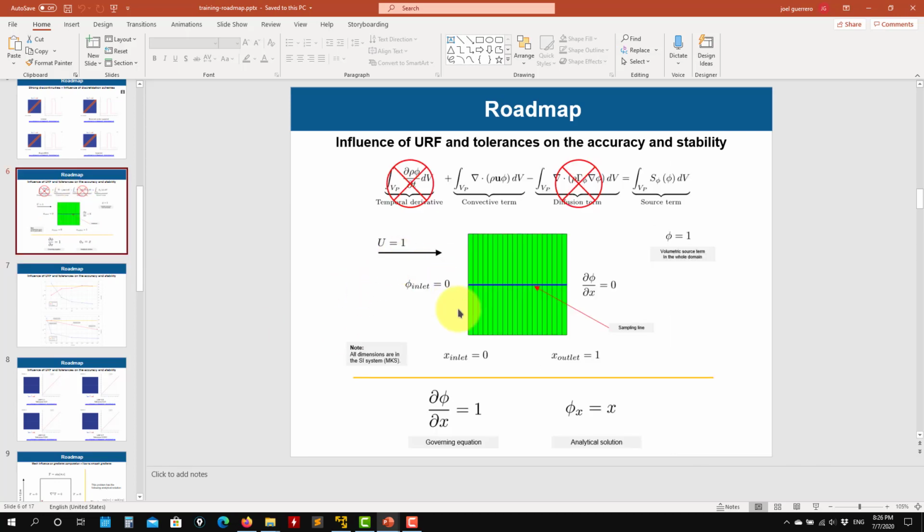Okay, this is the setup. Here we fix the value of the transported quantity to 0. Here we put our Neumann boundary conditions, and the domain is 0 to 1. So in this case, we're using a perfect mesh. We know how to deal with the correction, but feel free to use, as in the previous case, the same dimensions with triangles and polyhedra.